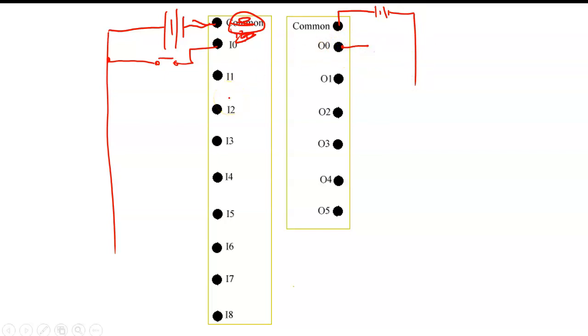So when you draw the connection to the PLC, the only symbols right now we've got in the program are examine if open, examine if closed, and a coil. The symbol for a coil. And we'll look later on at where the coil doesn't even have to generate an output. We'll look at our bit files as we go along. Sometimes a decision in your PLC program does not have to generate an output. It's inside your control. In motor controls, you'll learn those as control relays. A control relay is a relay whose contact does not control power to anything. It's just there for decision making, for logic, like ands, ors, nots, nors, and stuff like that. We'll learn how to hook contacts up there.